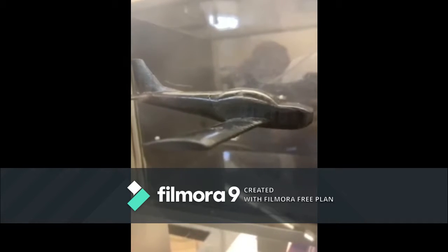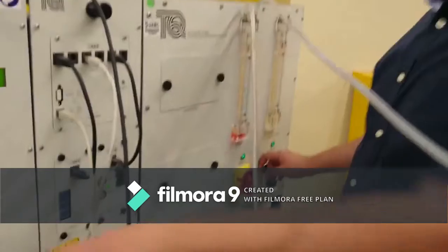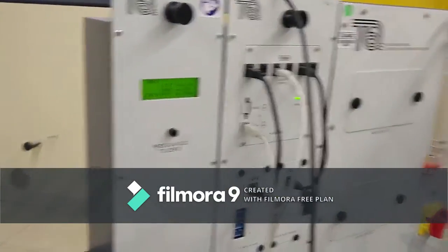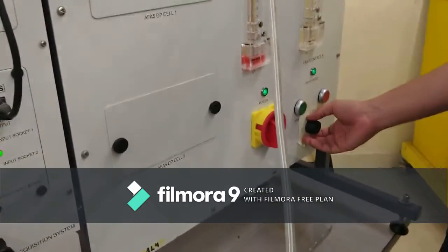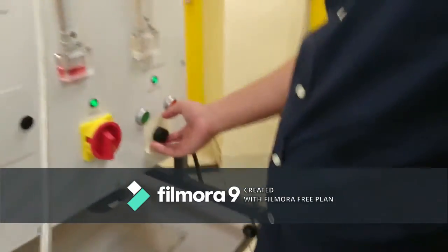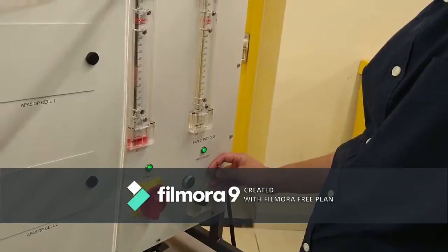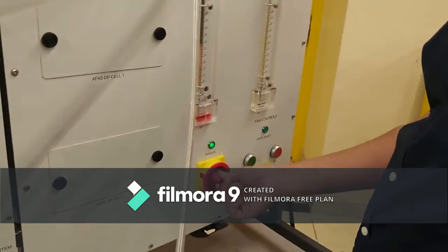We made sure that by adjusting the half-inch diameter rod to the fastener, the angle of the knob was in accordance with the plane's completely horizontal position. Once this was done, we increased the velocity up to 36 meters per second as seen in the measurements. So we can obtain the data to analyze the plots and the behavior of the forces of lift, drag, and friction moment. We just need to connect a USB cable from the tunnel user interface to our laptop and press play.